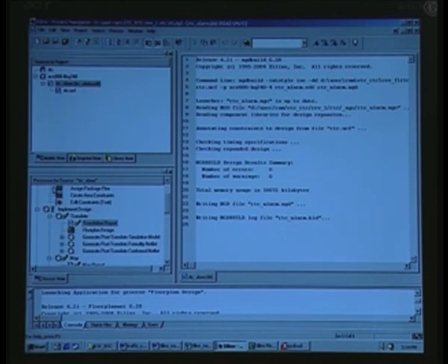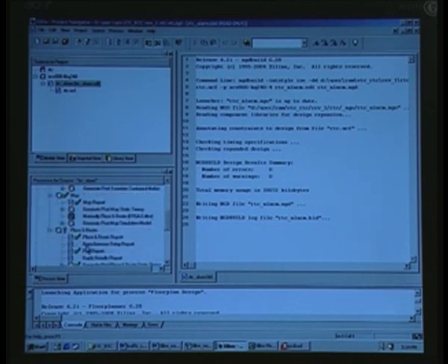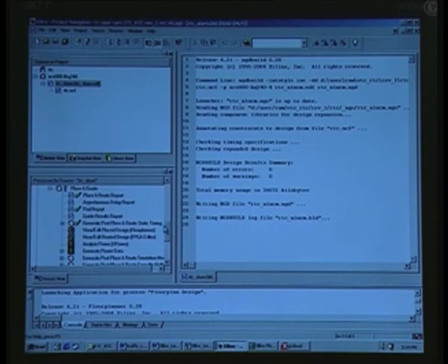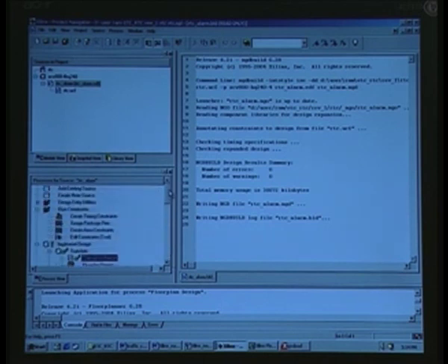And another window is processes for source, and here what is listed is implement design and map, place and route, all this. There are wide varieties of place and route, we will see one after another, and then finally to generate a bit file we need a generate programming file. I will show you a zoomed version in a minute.